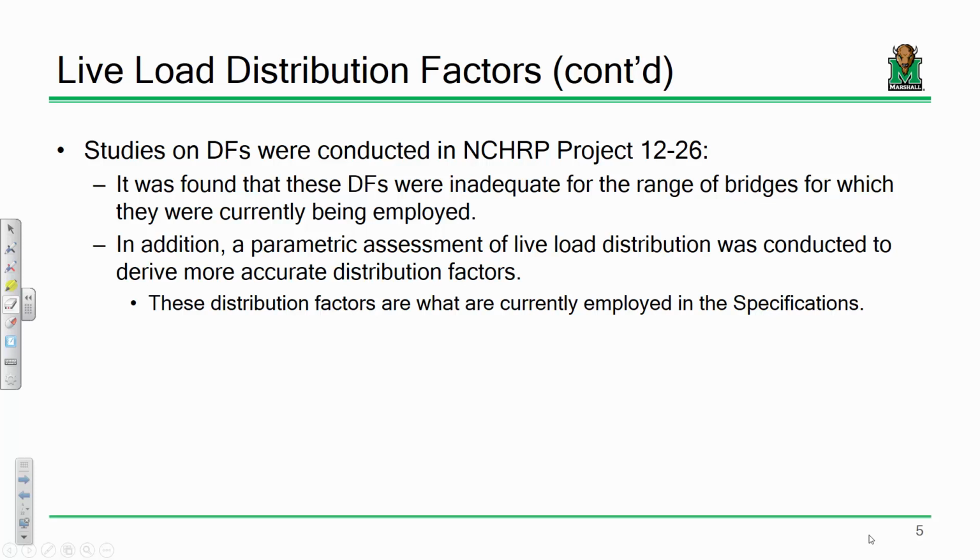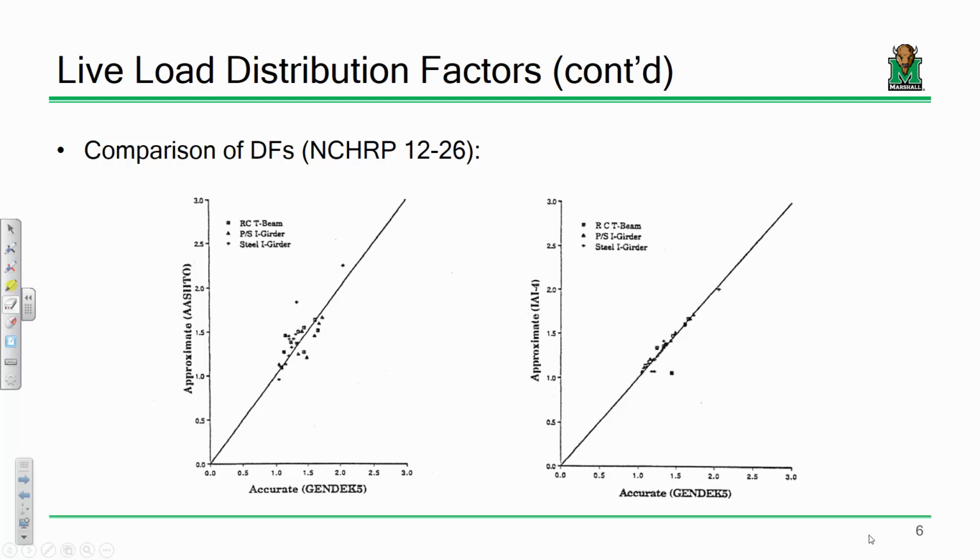Like what you'll find is that the moments on a particular beam will go down if the beam gets longer. That seems a little weird, but that's the facts because it's not just two-dimensional. It's three-dimensional. Loads go this way as well. Okay? So there was a study that was done by Ensign and Associates out in Sacramento back in the 80s, and they did a boatload of analyses to try and come up with better approximations and better equations for live load distribution factors. And these are the ones that are present in the spec.